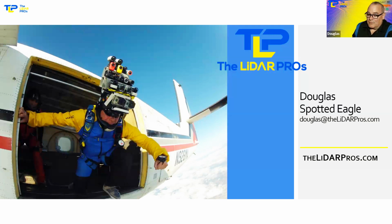Then, do we have any good ground-based solutions for photogrammetry and LiDAR? We absolutely do. We've got static-mounted LiDAR systems, and then for ground-based photogrammetry, things like the Ricoh Theta or Insta360, a lot of these cameras are capable of doing ground-based photogrammetry. Bear in mind, it's going to be significantly slower, but you'll also be building 3D models directly from the ground.